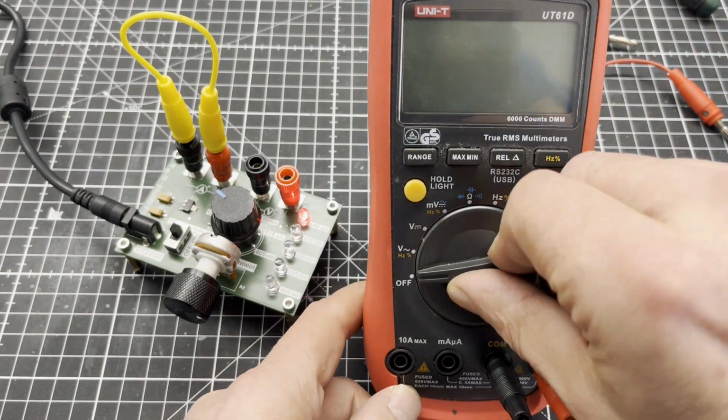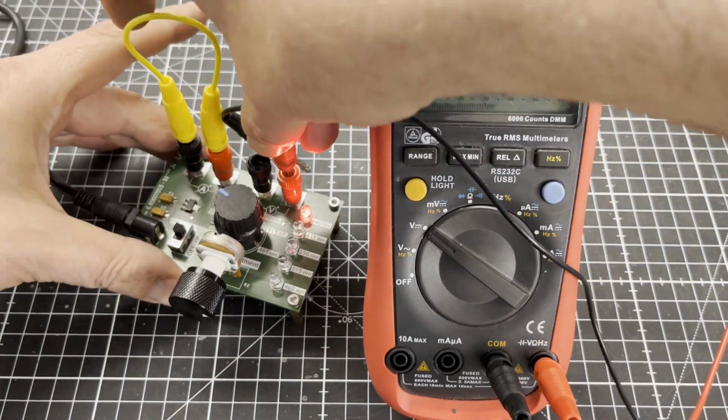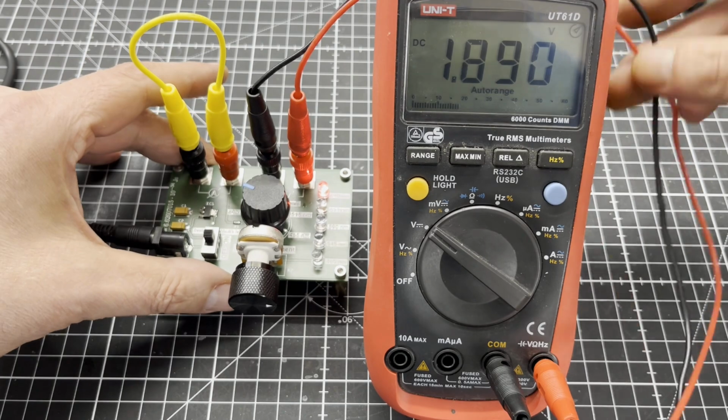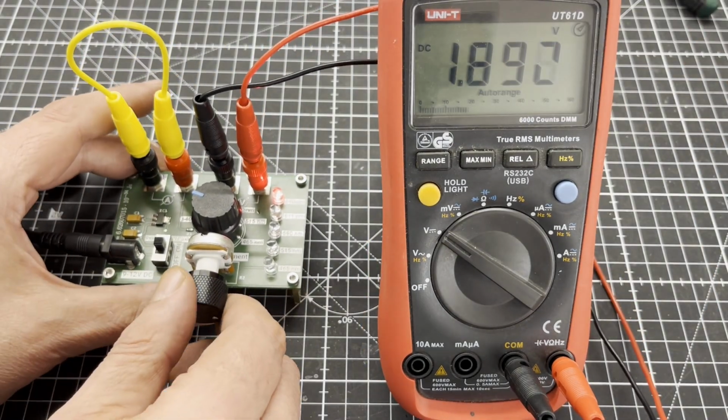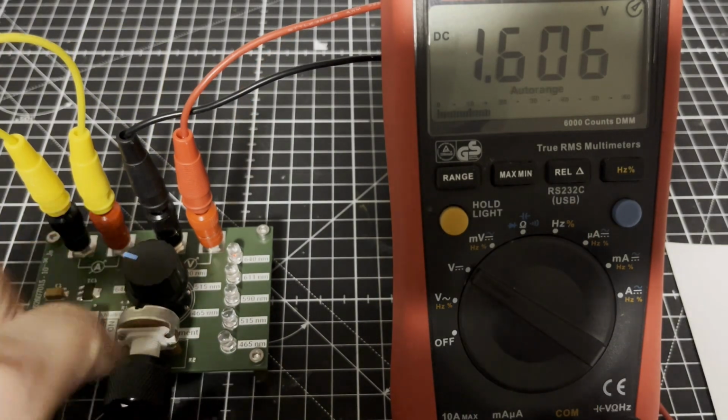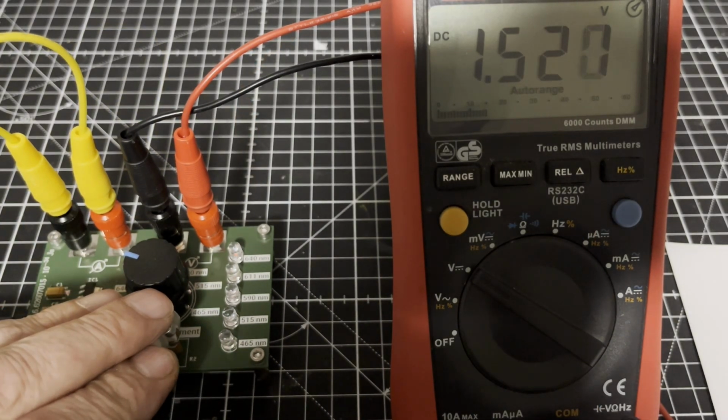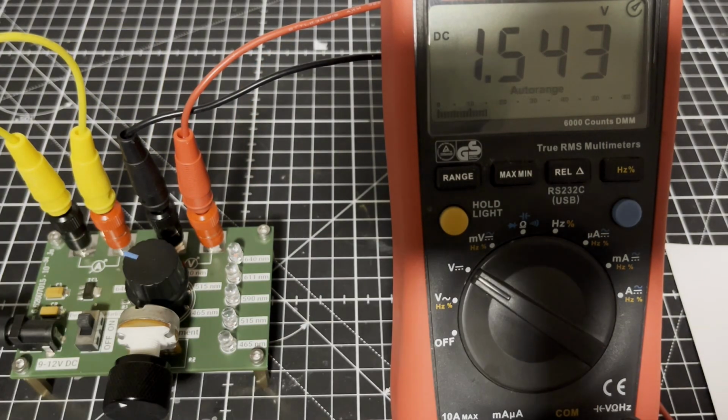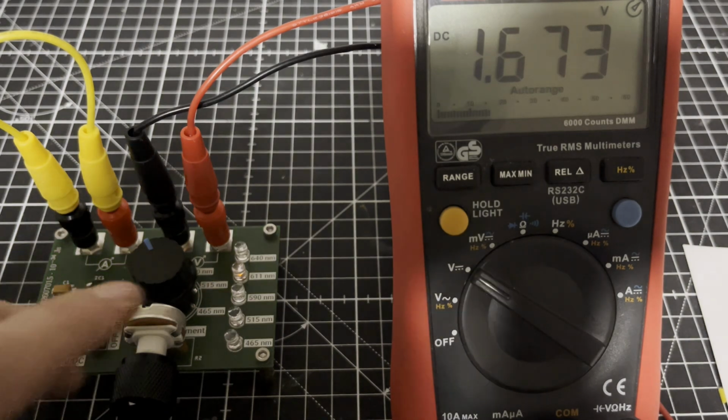For the experiment, a multimeter is now connected to the PCB and the DC voltage range is selected. The experiment itself is very simple. For each LED that corresponds to a certain wavelength, the voltage is measured when the LED barely lights up.